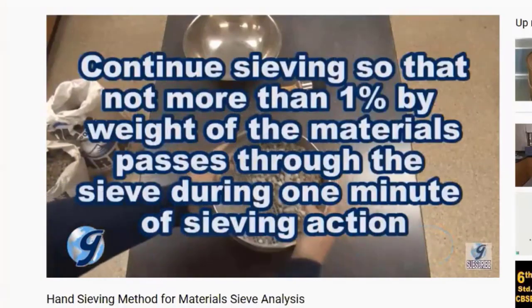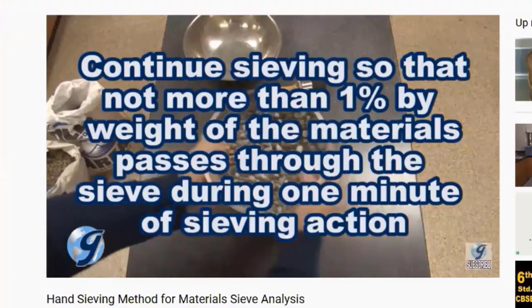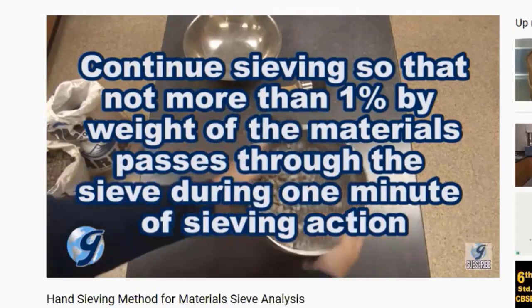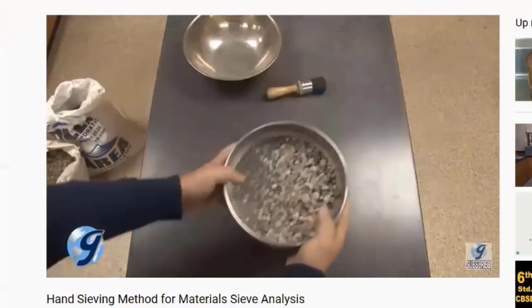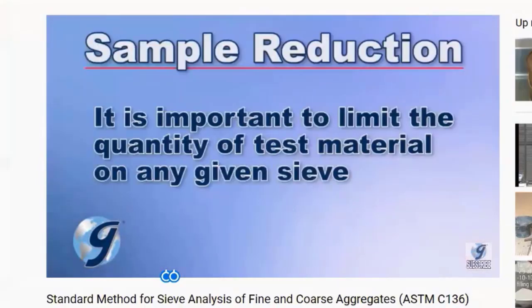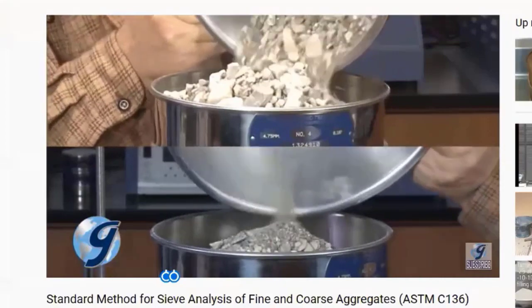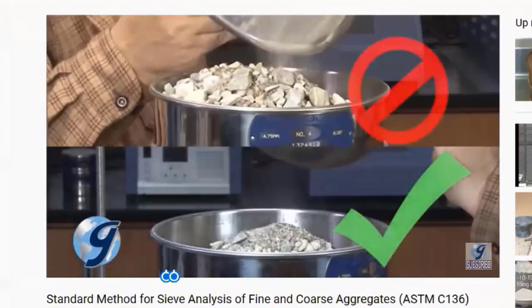Continue sieving so that not more than 1% by weight of material passes through the sieve during 1 minute of sieving action. This determines the compliance of particle size distribution so that all particles have the opportunity to reach the sieve openings a number of times during sieving operations.